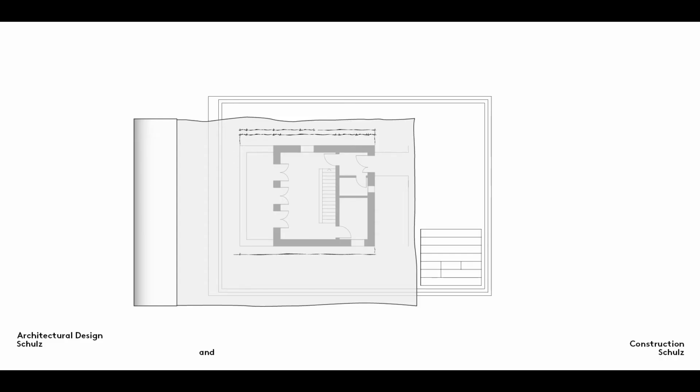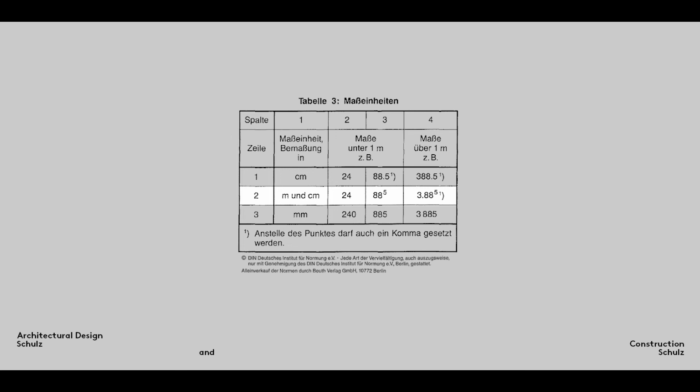Construction drawings contain lots of dimensions and dimension chains. To keep the dimension chains on your drawing tidy, you should sketch out the dimension chains you will need and where you might want to place them on a separate sheet of paper before adding them to your drawing. Once you have all the different dimension chains you need and have positioned them in an orderly manner, then you can inscribe them on your drawing. There's one further small but important point to bear in mind.